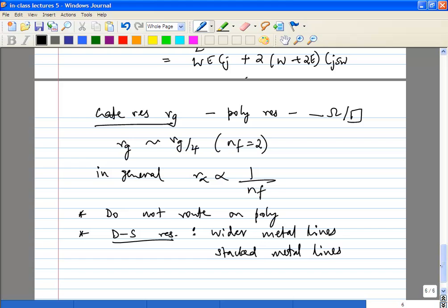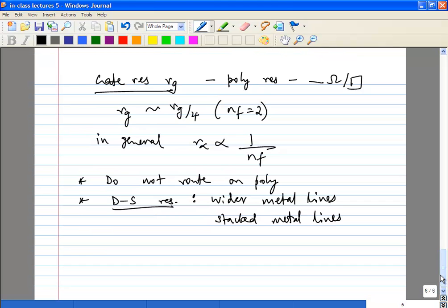Sir, you told one advantage of splitting the transistor into fingers. Remember that the gm is also a function of your number of fingers. If you make your transistor too small, there are two things you have to worry about. One is gm. The other thing is, for each of those fingers, you have to worry about the gain or performance, gm, whatever you're worried about of that particular cell, versus the extra parasitics you are adding by actually splitting it into a number of fingers.